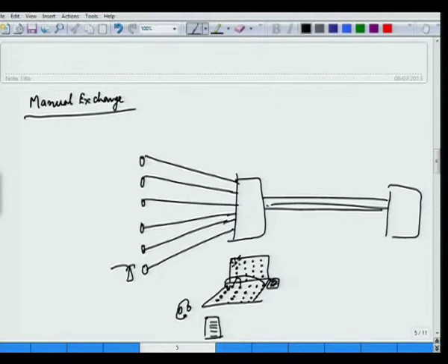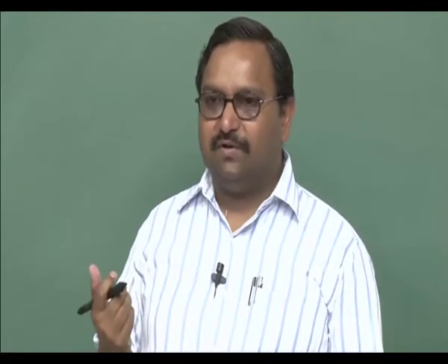For the next person, once she knows who that other person is to whom the call has to be made, she will use another what we call a ringing generator. Okay. So this ringing current has to be applied from here onto that particular jack. If this is the destination, ringing current will be applied here, which in turn causes the phone here to ring. Ringing current usually is not in the audio band, this is actually the current power which is being modulated, which will cause the ringing of the phone.